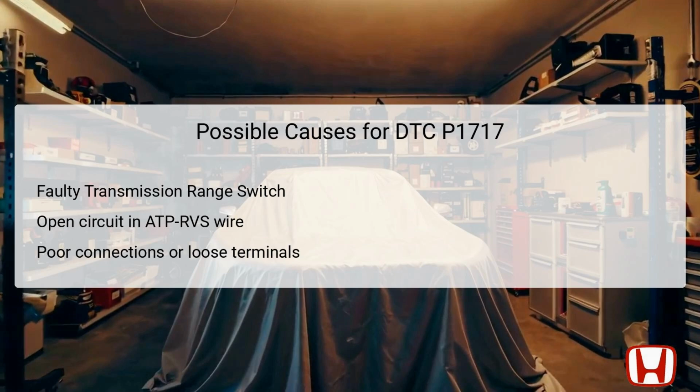Additionally, poor connections or loose terminals between the switch and TCM can result in intermittent failures and erratic behavior in the gear shifting mechanisms. In this respect, thorough inspection of the circuit and connectors is imperative to diagnose the cause accurately. This step is vital before moving on to replacing any component, as it ensures effective repair work.